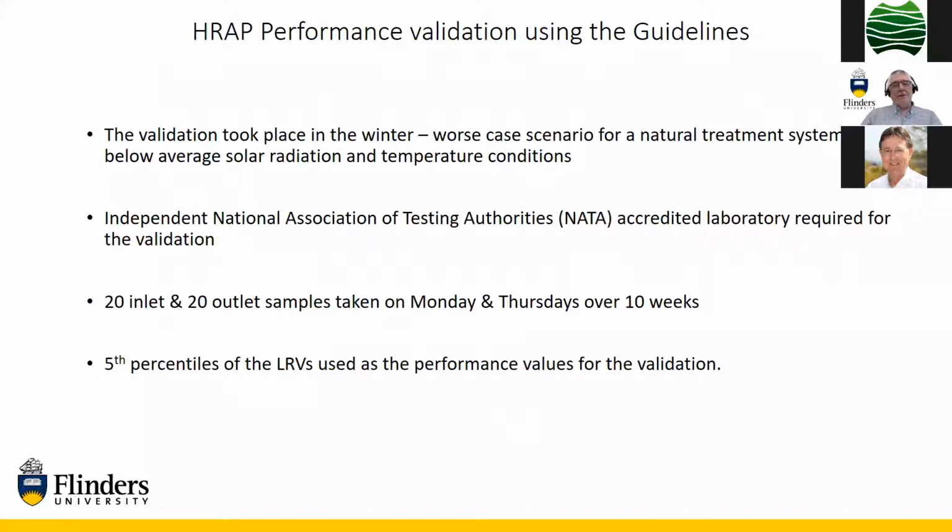This was all done in consultation with the Department of Health and Ageing in South Australia. And for these validations for natural treatment systems, the view is, of course, that we're relying on natural factors such as light and temperature to affect treatment and pathogen inactivation. And you'd expect that the worst performance of these natural systems would be in the winter. So the validation is a conservative validation. It's done in winter conditions.